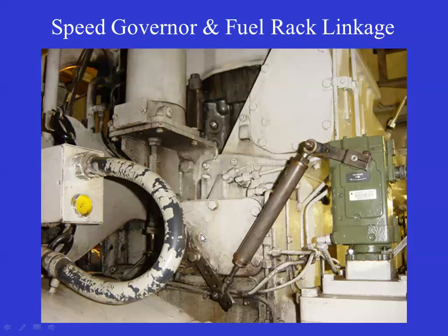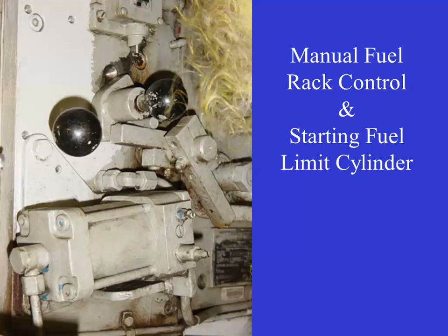This right here is for the start air system. When you start one of these engines, watch how it works, but that will limit your rack on startup so you don't overspeed. So that's your starting fuel limit cylinder.